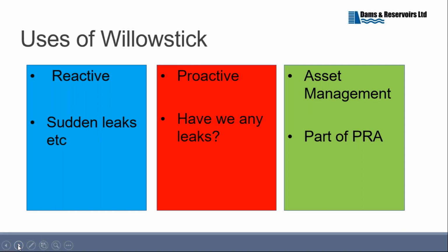And when we look at the use of this technique in asset management, it's a repetitive process where one can assess a dam perhaps in one particular year and then go back 5-10 years later, reassess it and see that there hopefully has been no deterioration, but in some dams we do see a deteriorating process taking place, and then you can intervene, because obviously the consequences of failure are large: lawsuits and fines and penalties and even getting locked up, and one just doesn't want to go there.